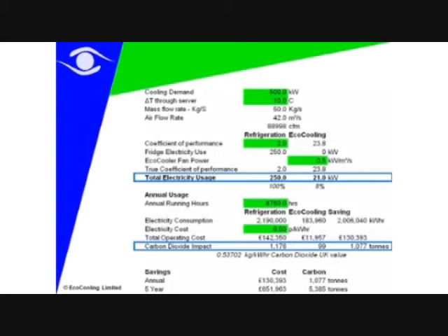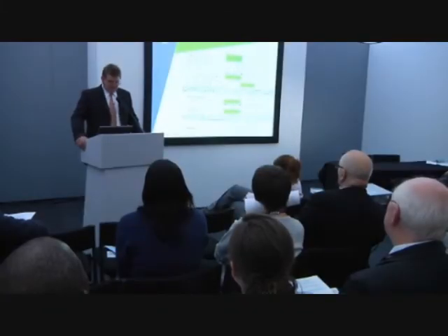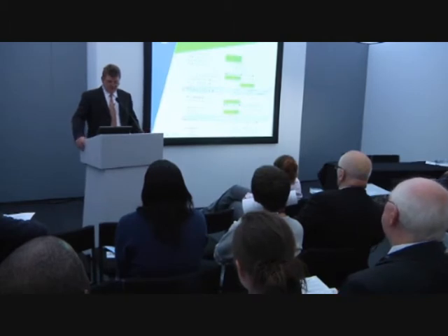The next stage of that spreadsheet, you will see there's a comparative cost, two columns between refrigeration and an Ecocooling CREC system. The coefficient of performance of refrigeration in a PUE 1.6 data center will be about 2. That means for the 500 kilowatts of IT load, we will be putting 250 kilowatts of energy continuously into the cooling system.